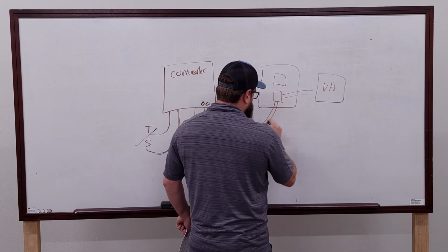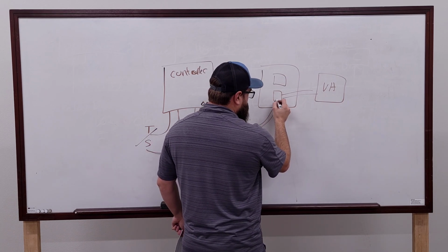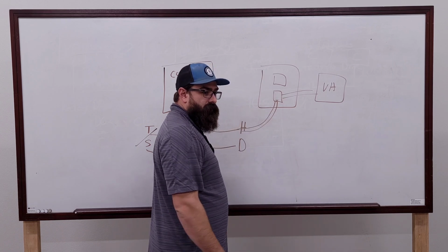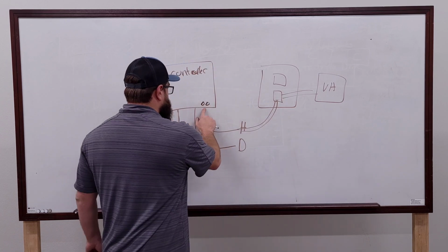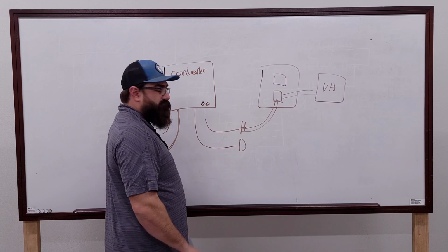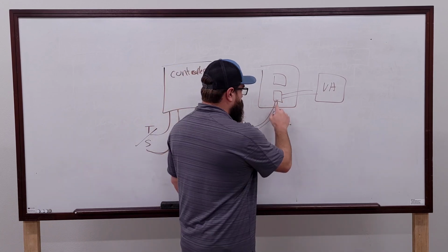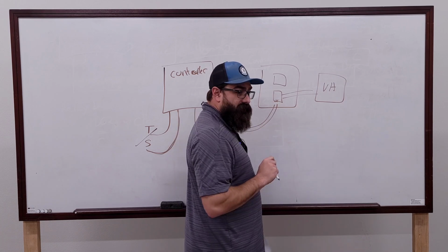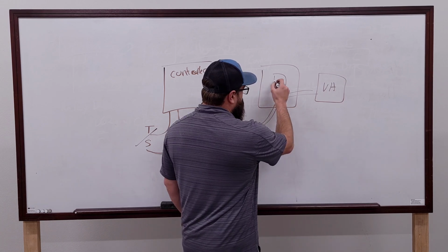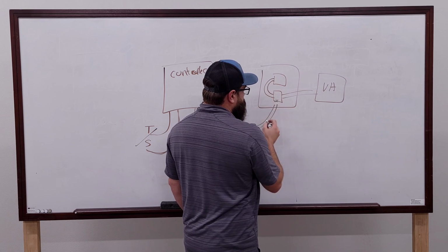I would come in here and I'd measure here and I'd have nothing. So I'd unwire this, check that again, I'd have voltage, wire it back up, come over here, nothing. I'd unwire this, check it, I'd have it. Well, these guys were all sharing 24 volts.